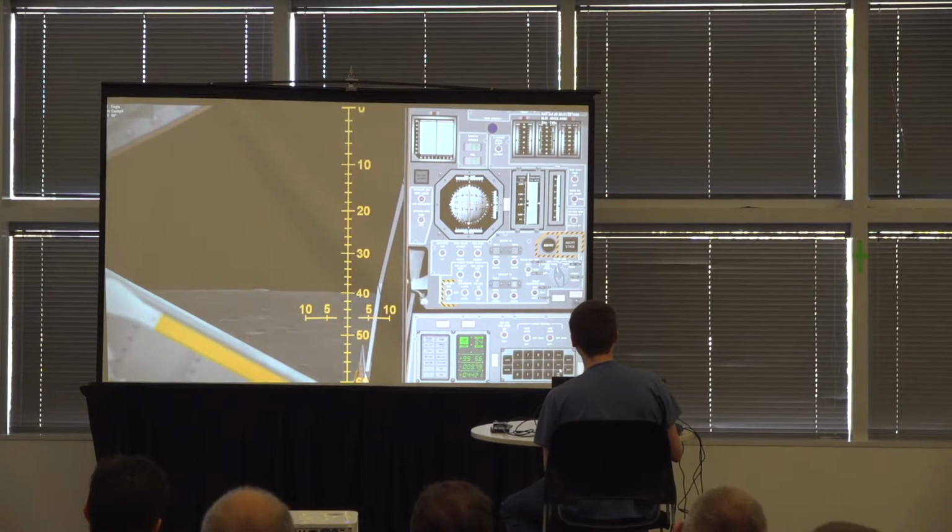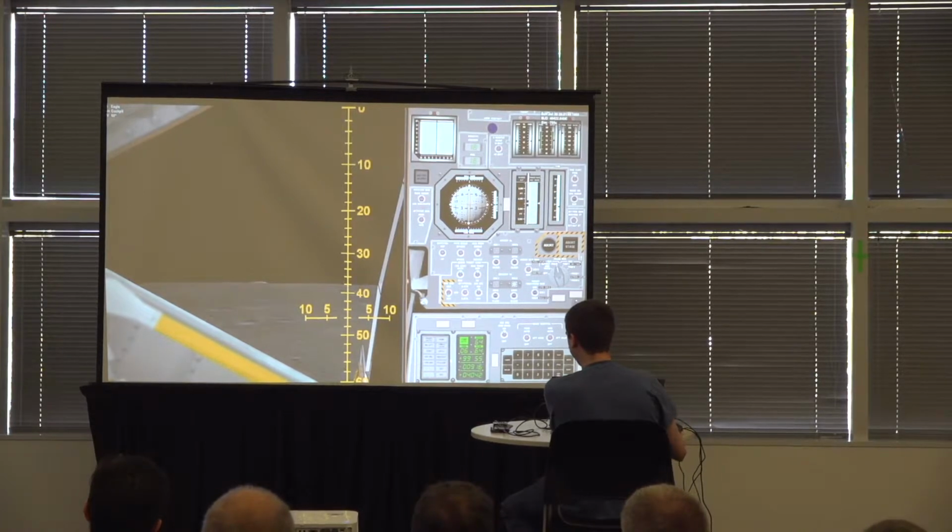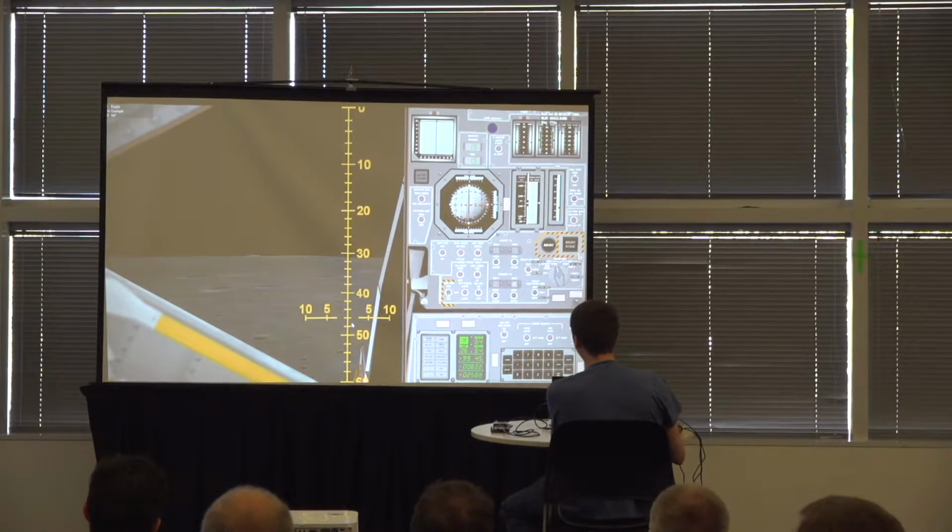And if I hit proceed on this screen, I can use my joystick, just quick deflections forward or to the sides to change the targeted landing site. So I press forward a couple of times, the lunar module is pitching forward, and now, according to the landing point designator, my landing site is going to be around here. So I can do that as much as I want. The number here is the number of seconds that I have remaining to make those designations, so I have quite a bit of time to do it.